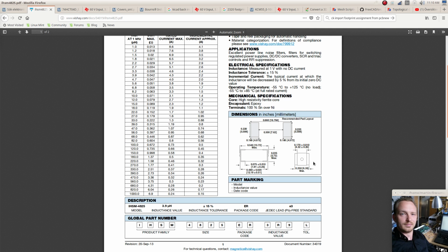Now the pins: you don't actually specify the width of the pins in the IPC name, so you could pick default values, but if you need to specify, you really need a way to do it. So let's see. The recommended width of the pad is 5.58, which is clearly more than what we have.